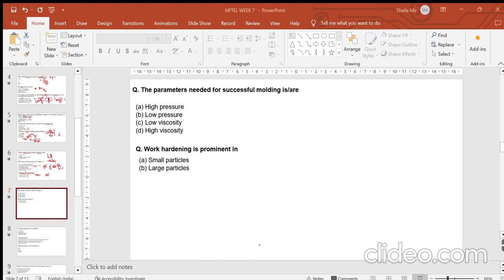If it is a metal, it will strain harden, but if it is a brittle material, it will fragment, it will break into pieces. So it is based on what kind of material you have. These are the stages of your compaction process. So you are asked in which of the following, aluminum, gold, tungsten, Al2O3, you expect strain hardening to occur. Aluminum and gold, right? Because they are metals, so you expect strain hardening. Tungsten and Al2O3 will fragment because of their property of being brittle. Okay.